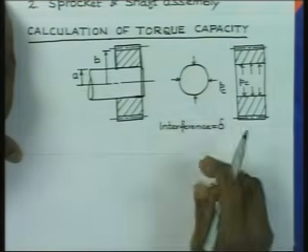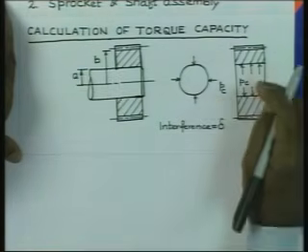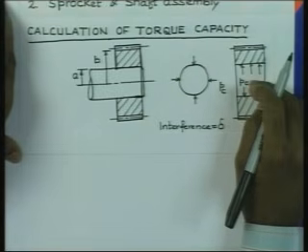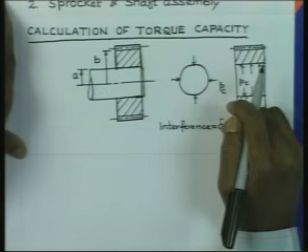we have considered both the components in the shrink fitting to be hollow, but when you have a solid shaft, then what is the distribution of stress? So, in order to calculate the interference, what you do is that you try to consider the contraction of the inner cylinder under the action of the pressure PC and the expansion of the outer cylinder under the action of same pressure, and you sum these two and make it equal to the interference.